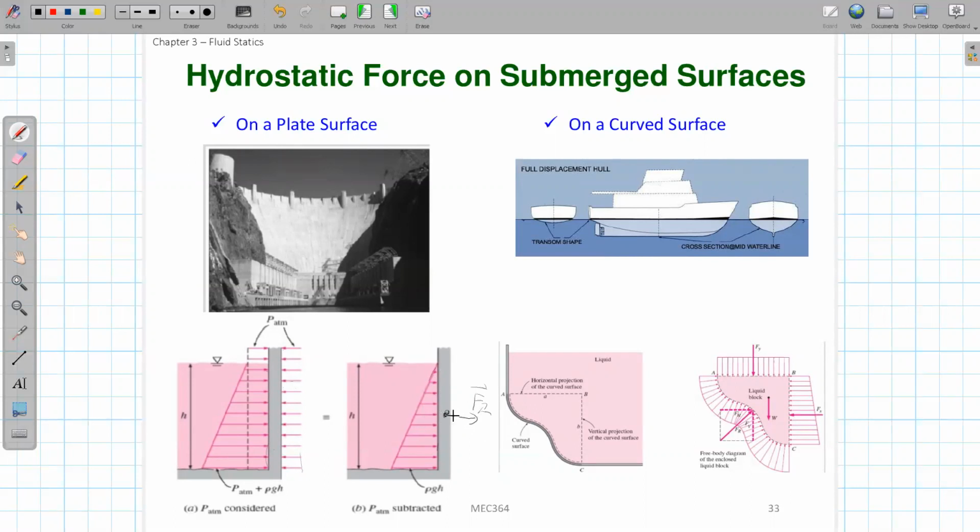We try to use a single resultant force and also find a point location, so that the force and the moment created by this single force, taken about the bottom or the top or somewhere, will be equal to those of the overall pressure force. If we can find that, we make the problem simpler, because we can reduce the surface pressure to a single force.